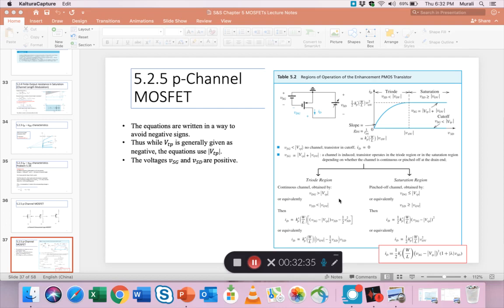So the point is, all the relationships are similar, but you have to watch out where the signs get turned around. So for example, with an NMOS, you know that the gate has to be positively biased. The source is grounded for an NMOS, the gate is at a positive, and then the drain is also at a positive, right? For a PMOS, it's flipped.